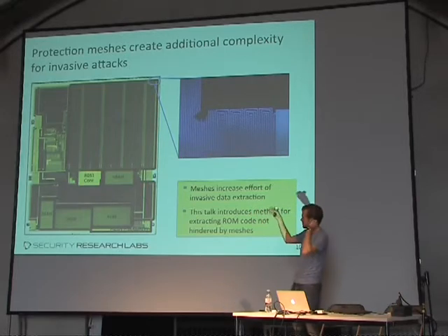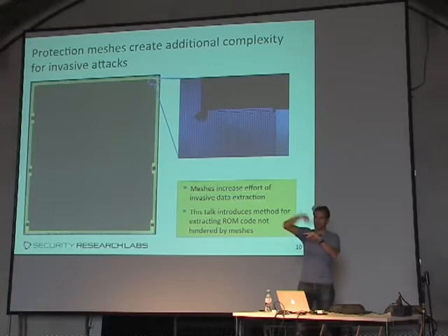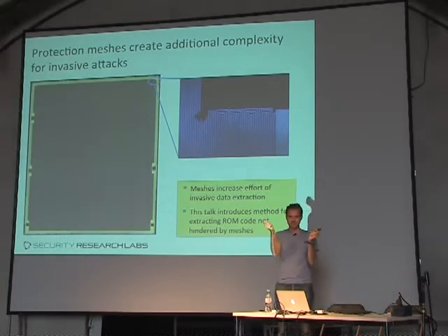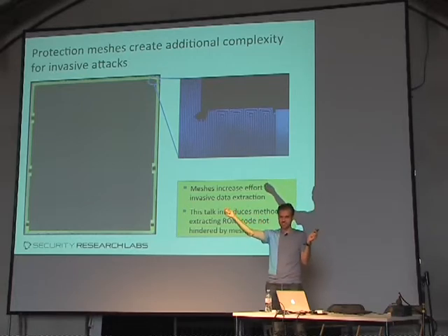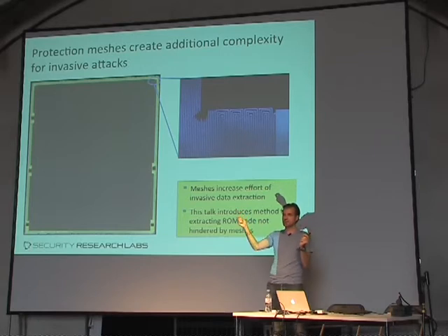And this has, I think, 4 metal layers up to this point, and then I put a 5th metal on top. That's just a little snake going all the way across over and over again, and the chip tests whether the snake still exists. It takes a measurement from one end to the other, and when it's not intact anymore, the chip won't boot.